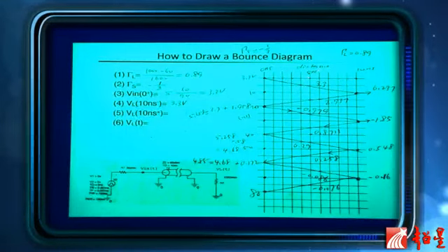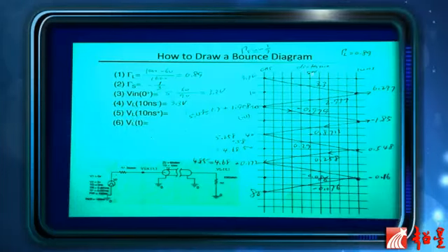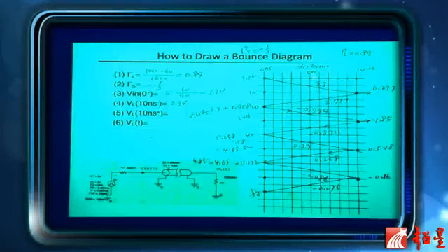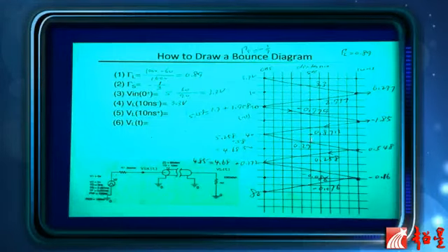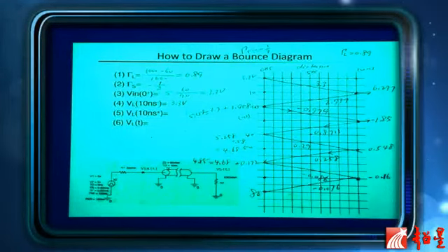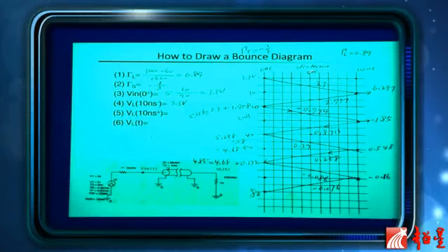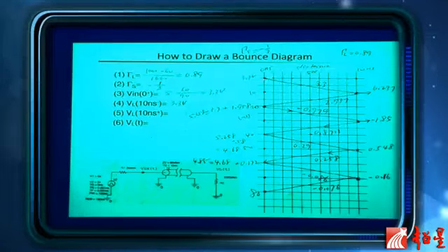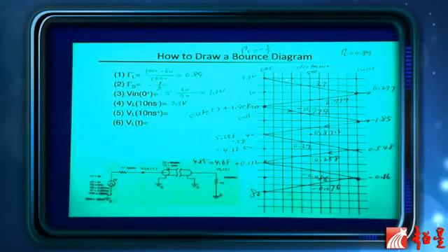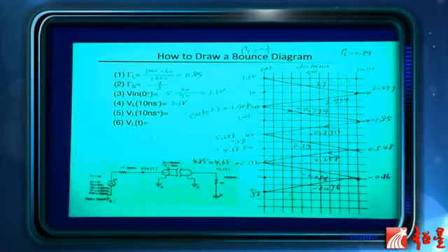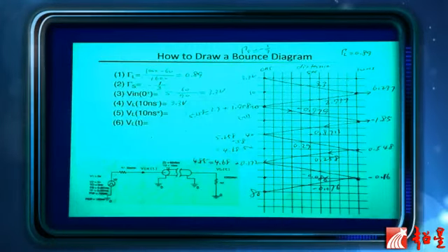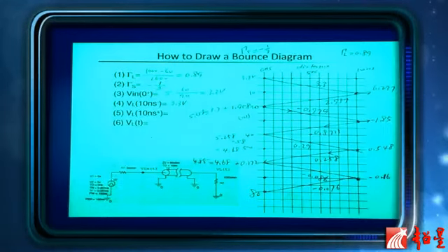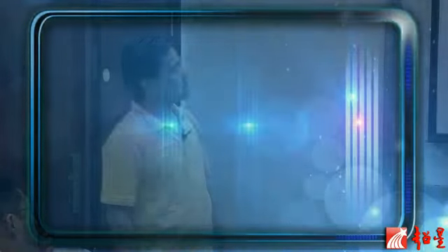For example, to find the middle of the line, at 5 nanoseconds, you just draw the line and add all the voltages at the proper time, and you can find the timing waveform of the voltage at this point. At any given distance, you just add all the voltages at that point to find the actual values of the timing waveform.